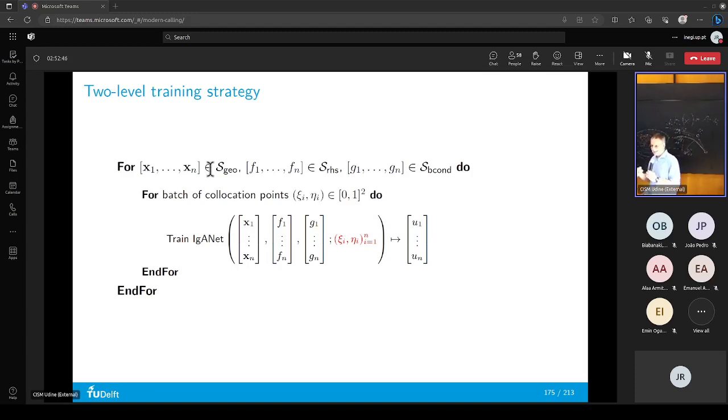In practice in engineering, you very often know exactly what typical shapes you have. The rotor will never look completely different. It might have a little more spiky or a little broader or a little thicker teeth, but it will always resemble a rotor or a gear. A gear looks like a gear. It might be a little bit modified in the shape, but it doesn't look like a car. So be meaningful, decide what your geometry database is on which you want to train.